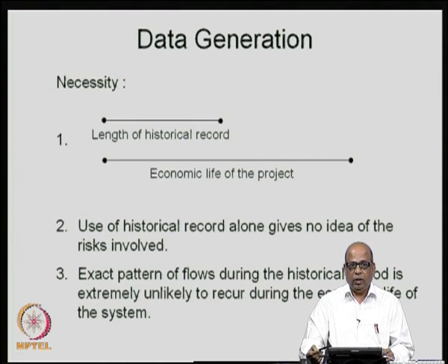Another reason why we do data generation is that if you use only this historical record, let us say you had 30 years of data and you make all the decisions based on just this one sequence of 30 years of data, it will not give you an idea of the actual risks that are involved, especially when you are looking at the risks due to flooding or the risks due to droughts, hydrologic droughts, and risks due to inability of the system to generate the necessary power and so on.